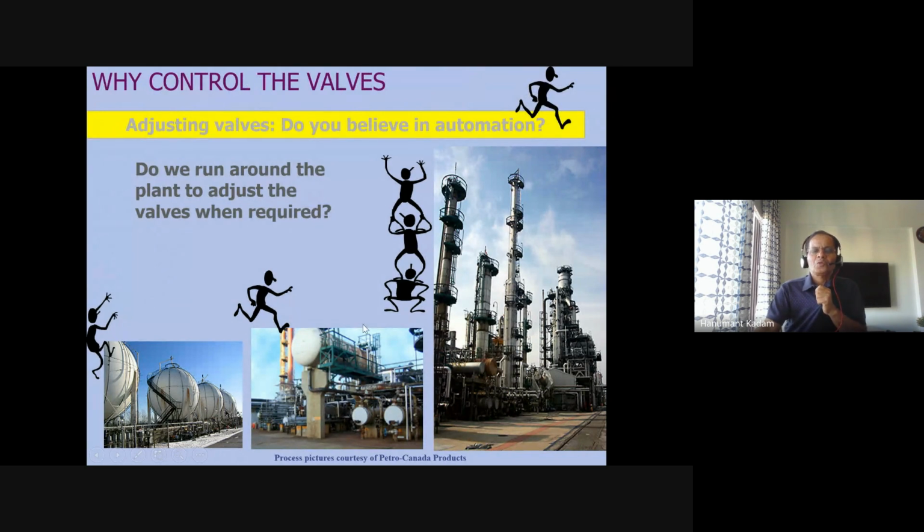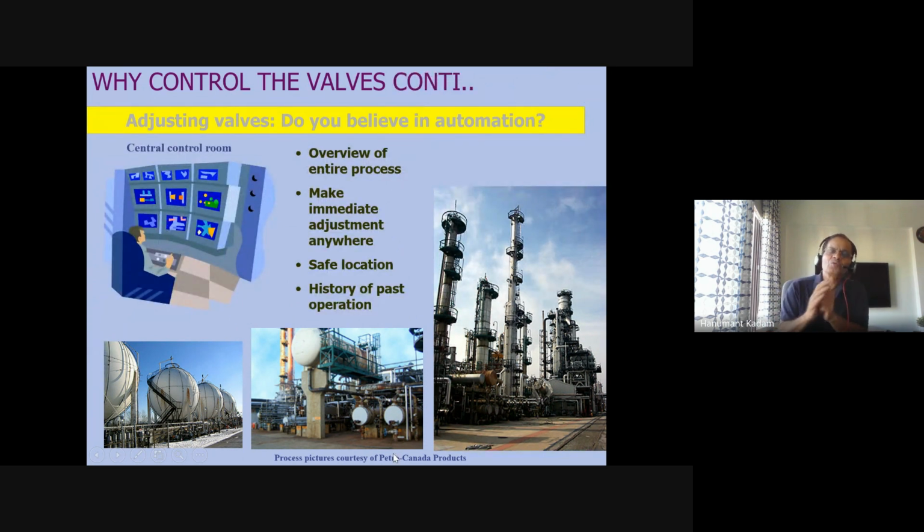So you need not go up to operate the valves. From the control room you can operate it. The earlier picture was showing that you have to go to the field location, which is very critical to reach. Now it is not required. From the DCS control room, sitting here comfortably, you can operate your critical locations.